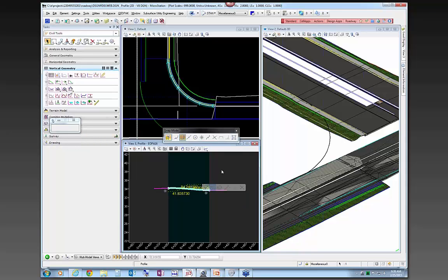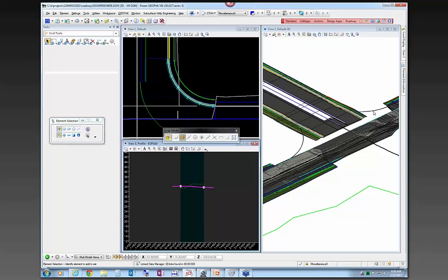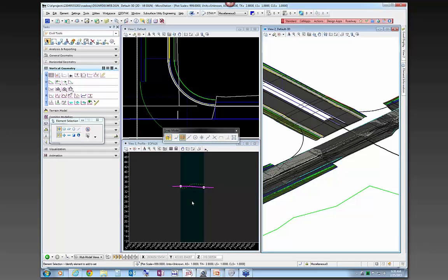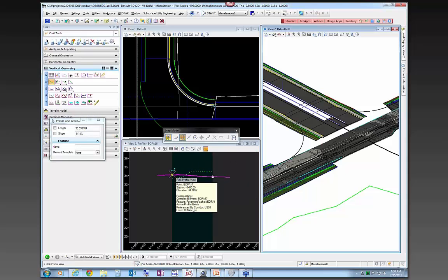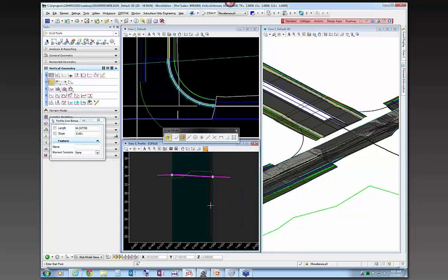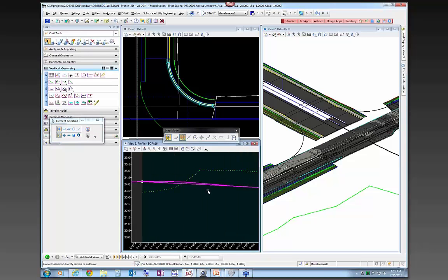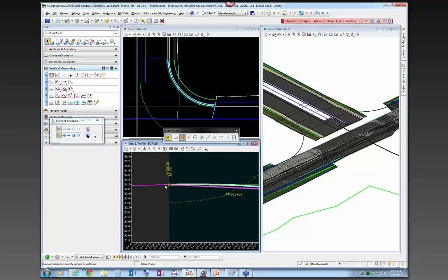In this data set, this is the most difficult lines to get in 3D, just because these commands can be fickle in this data set. But now once I have these 3D line strings, I have them out there that way. You could have also used a quick line between points if you wanted to, and just drew a line from one point to the other. And if you're going through the data set and you want to do it that way, just to get a line in there, the only issue obviously is that this is the straight line and this is the reverse curve line. So you're not really truly at a tangent, you have sort of a little break here.